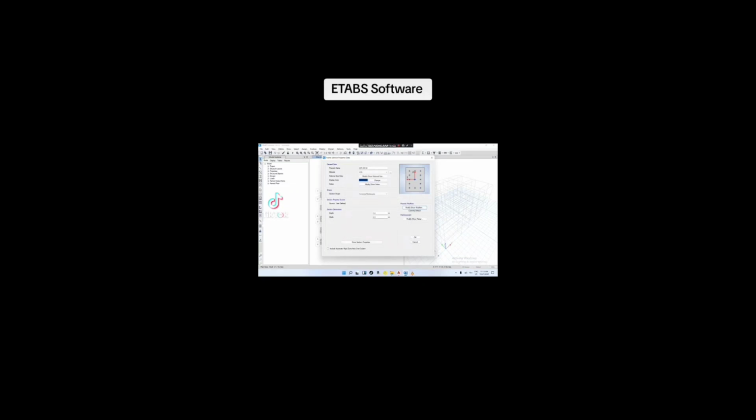And this, I will modify the reinforcement. I will choose beam. This is column. In the beam, I will see how much the cover is: plus the diameter over 2. If I choose diameter 10, plus cement, it all comes to 4, like this. I will change it to meter, 0.04. This is for the cover of the concrete, the bar reinforcement.